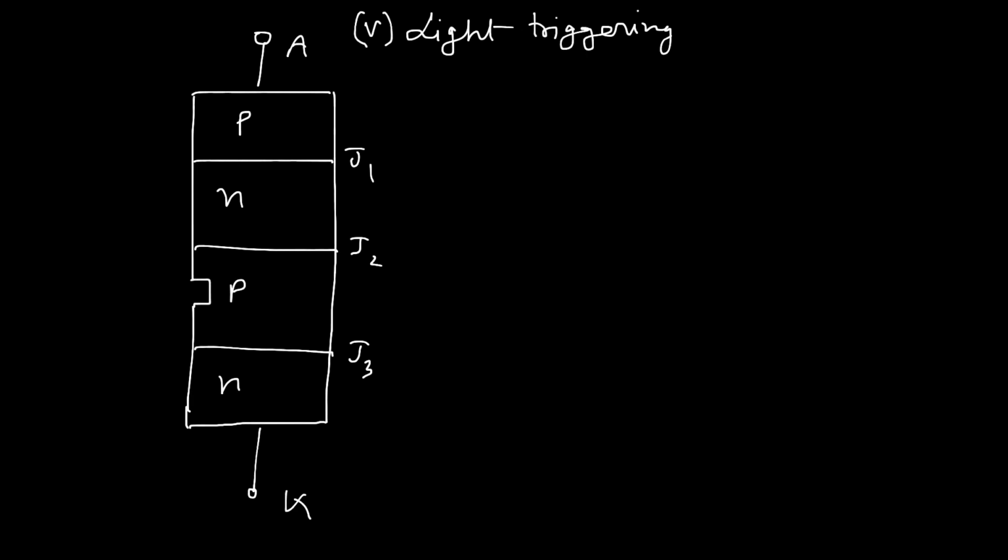That is why the density of the majority carriers can be increased by internal collision. That is why it will provide a huge avalanche, and due to this avalanche, a huge amount of carrier charges will be increased inside the P layer and the N layer. That is why the depletion layer across the junction J2 will be reduced, and once it vanishes, the device starts working in the forward direction without any disturbance.